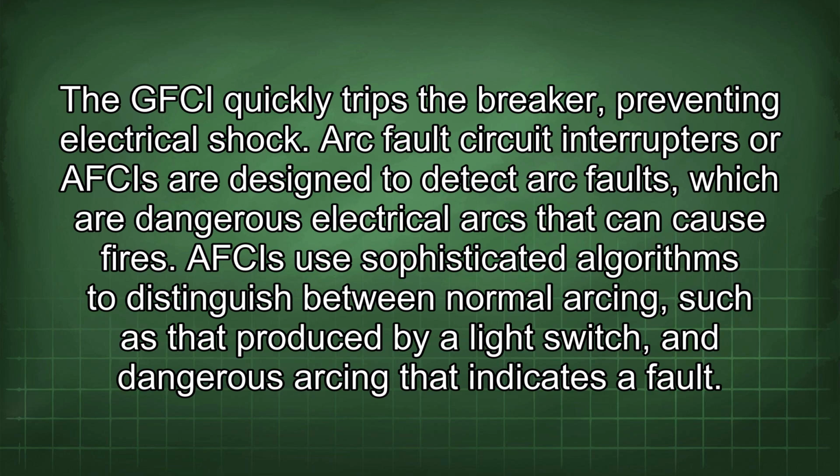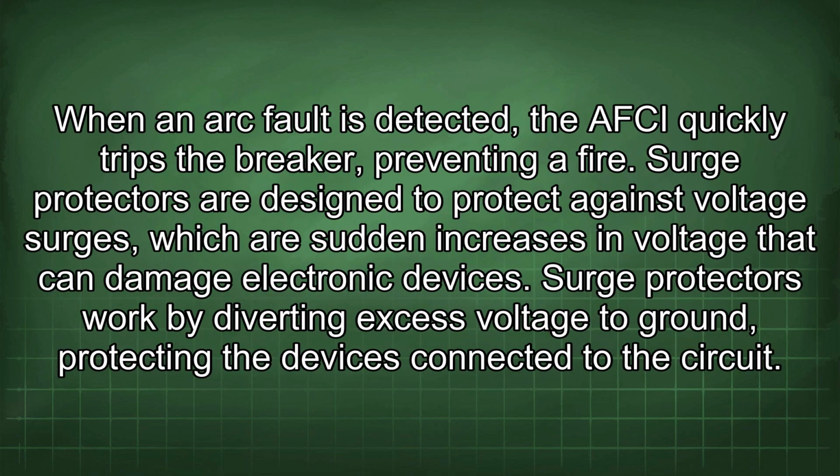Arc fault circuit interrupters, or AFCIs, are designed to detect arc faults, which are dangerous electrical arcs that can cause fires. AFCIs use sophisticated algorithms to distinguish between normal arcing, such as that produced by a light switch, and dangerous arcing that indicates a fault. When an arc fault is detected, the AFCI quickly trips the breaker, preventing a fire.